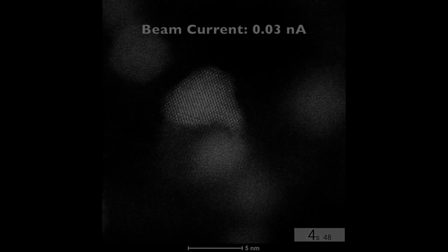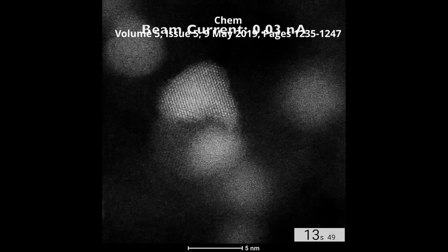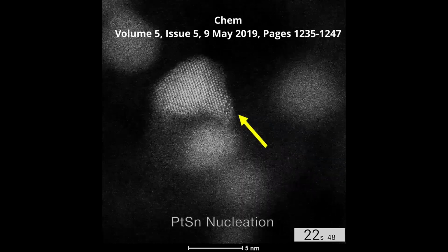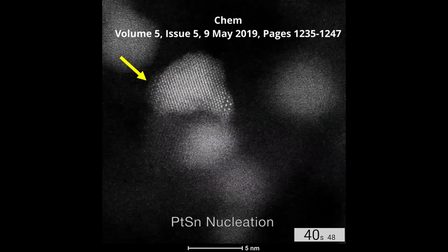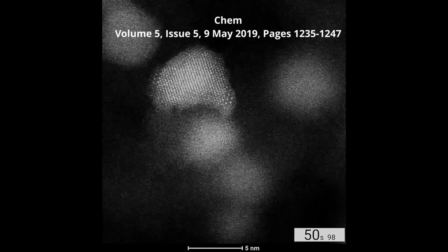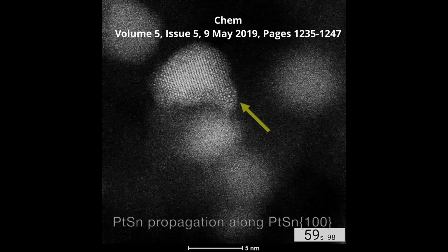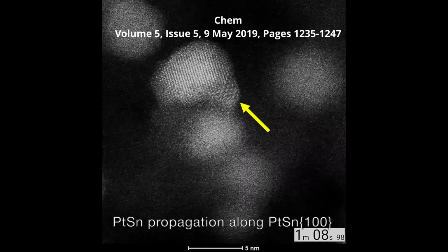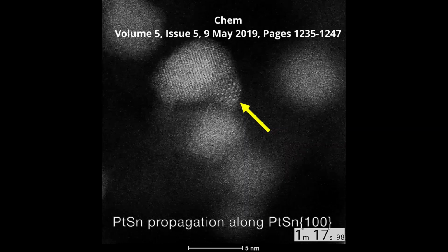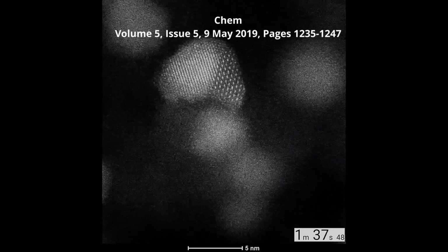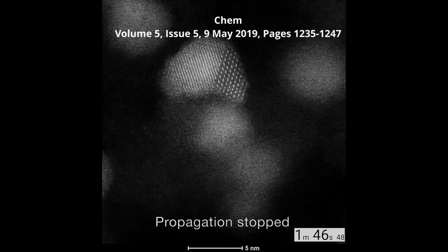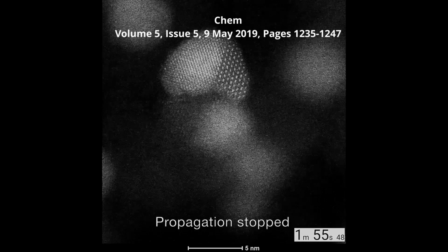As a conclusion, I'd like to say that the current processes employ chromium supported on alumina or platinum-tin supported on alumina catalysts. This catalyst and the technology have been advanced to the point where the reaction can be run continuously for several years.